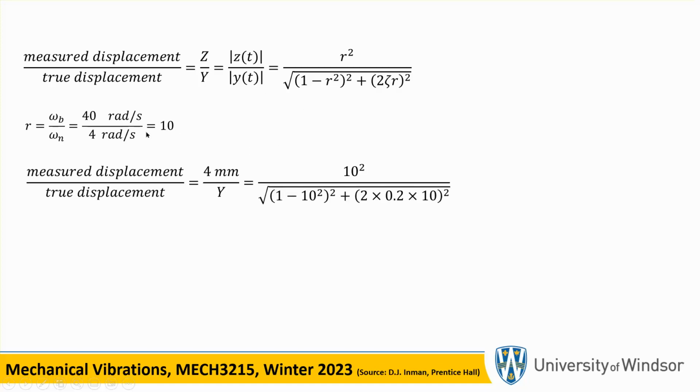So you are actually in the seismometer range, remember, that's good. Otherwise, what we wrote down is not true. So 4 over big Y that we are trying to find, we just plug in the values and get big Y, which is 3.06. The ground, or that platform as a unit, is moving up and down at 3.06 millimeters.